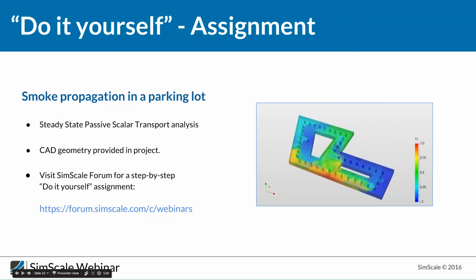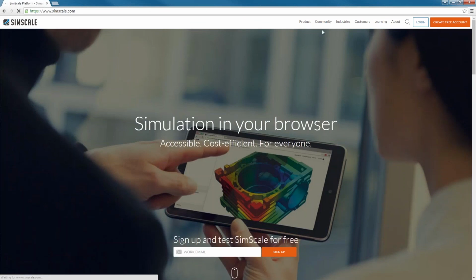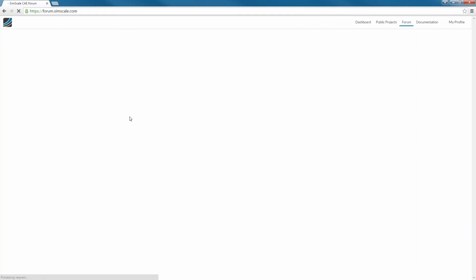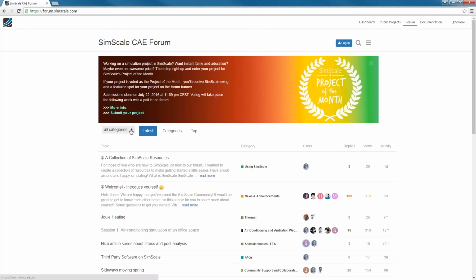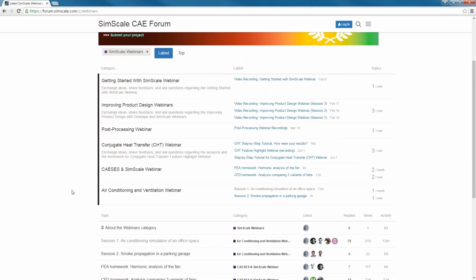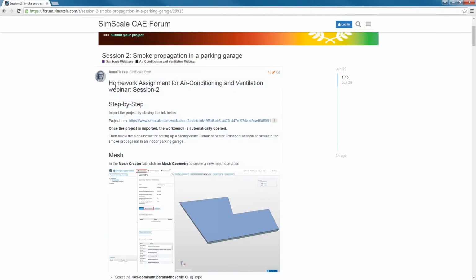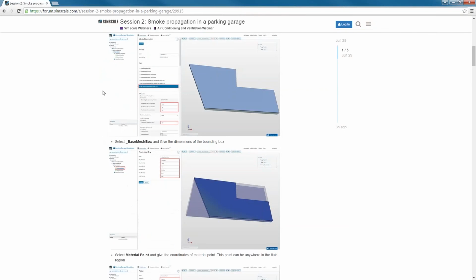Let me show you first how to get the project, and then we move forward with the rest of the webinar. So if you come here and go to the forum, in the categories you can simply switch to SimScale webinars. Here we have the list of the webinars. At the bottom we have the air conditioning and ventilation webinar. You can see we have entries for both session 1 and session 2. In session 2, you see a very nice step-by-step tutorial on how to first get the project, which already has the CAD model inside, and then create the mesh.